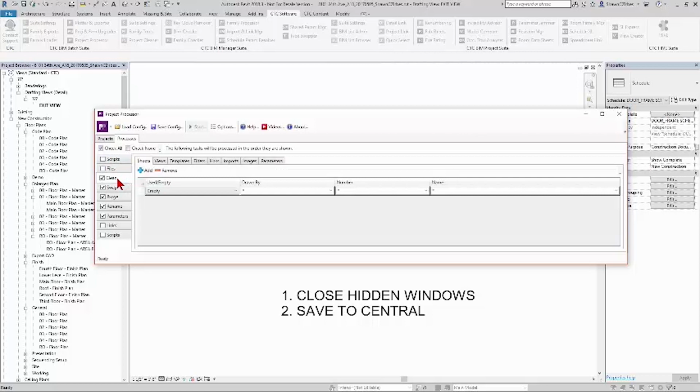You can also clean the models when they're open. So it'll automatically open up a model and then run through anything you're actually processing. To clean something, I can clean sheets, views, templates, all these different options here across the top. And this can be a rules-based cleaning. Like in this case for my sheets, I'm deleting any sheets that are empty. It doesn't matter who drew it, what the sheet number is, or what the name is. If it's empty, I'm deleting it.